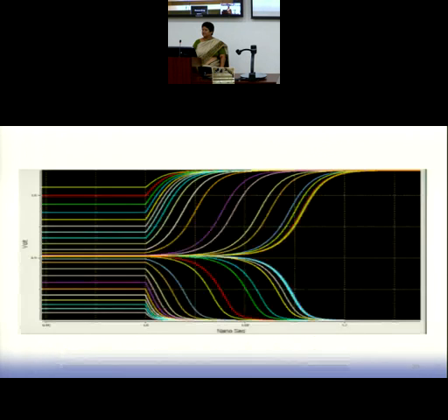Now to understand, normally if you have a master-slave configuration of a flip-flop, naturally the first one, whichever has the input, is going to face the metastability problem. It is not a problem for the slave. The slave is simply acting like a buffer. It's mainly the first one to which the input is fed, and you have setup and hold time violations over there.